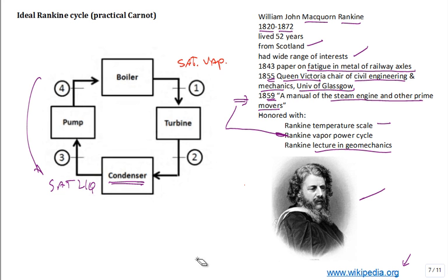And then you have much less work to drive the pump. The pump takes a lot less work to boost the same pressure to go from 20 kilopascal to 8 megapascal. It's a lot cheaper. A lot less work required per kilogram that goes through the device called a pump. A lot fewer kilojoules per kilogram that goes through the pump to boost the pressure, the same pressure difference.